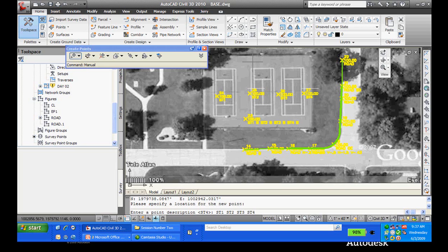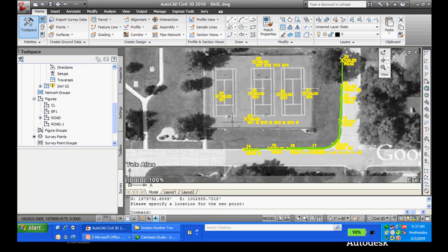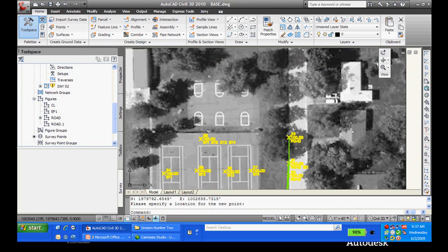Absolutely not rocket science. Doesn't matter what collection equipment I'm using, if I'm using Topcon, Trimble, whatever. When I shoot the point, I apply the code. It'll do my line work for me. All right? No special notes, no fancy recall statements or anything like that. All right? That looks good. I'm going to do one more thing before we process this. Let's take a look at a quick example of where I pick up a driveway, perhaps. All right, how this is going to work.